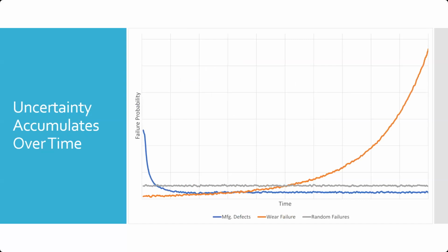And then there's another layer here called random failures, and these are where there really isn't a good reason that something failed, but it did. Oftentimes it can be attributed to environmental and operating conditions, in addition to wear failure, as certain parts get overheated or overstressed, and outside of the normal wear curve. And so those constitute random failures. It can also be parts just get damaged from handling, or from installation or removal, or transport. So that all falls in this random failures category.